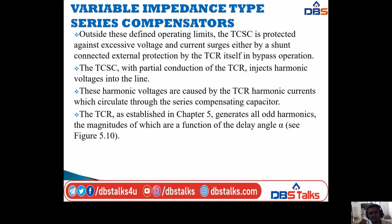These harmonic voltages are caused by the TCR harmonic currents which circulate through the series compensating capacitor. As established in the previous chapter on shunt compensation, the TCR generates all odd harmonics, the magnitudes of which are a function of the delay angle alpha, as shown in equation 5.10.